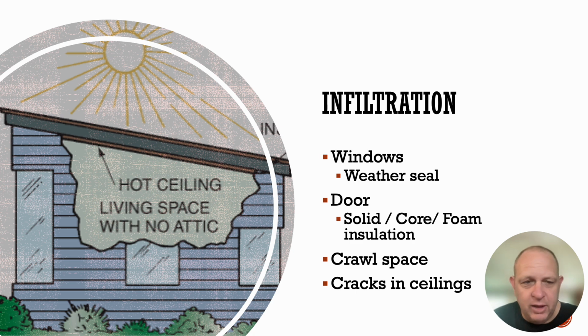During the construction of the house, plumbers, HVAC technicians, and electricians will drill holes into the studs and then up into the plates in the ceilings. And you don't see them because they are behind the drywall and behind the plaster walls. But if they didn't seal those holes, you're going to get air movement from the actual structure out through the attic space. So sealing up holes is a very effective way of preventing infiltration coming into that house.